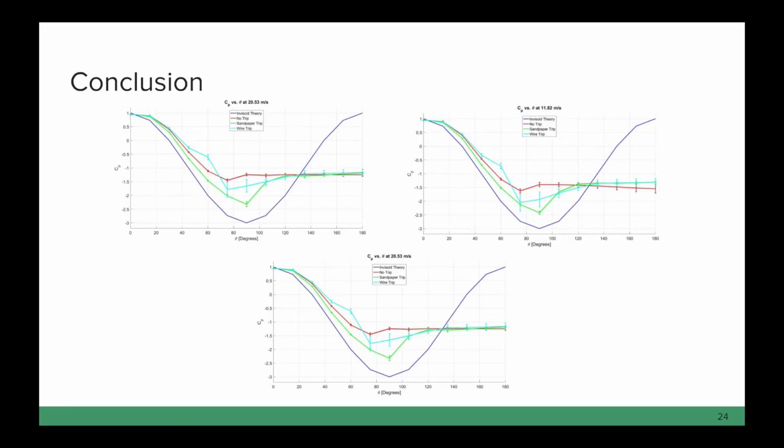Turbulent flow will then allow the flow to separate at a later point, decreasing the gradient of the low pressure region and in turn decrease the pressure drag on the bodies. The flow on the surface of the cylinder did not mimic an inviscid flow and therefore can be identified as viscous. Given that the flow is viscous, data from the cylinder produced with and without the trip strip was compared. The data showed that each type of trip strip reduces the gradient between the high and low pressure regions.